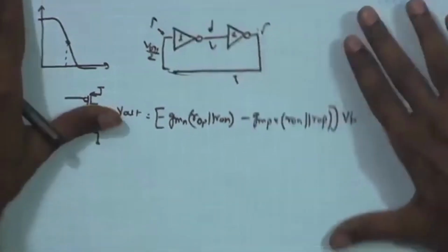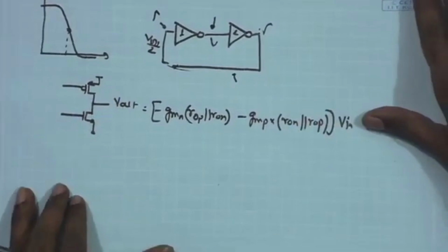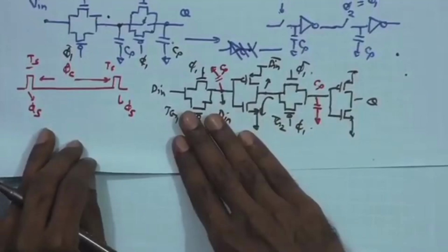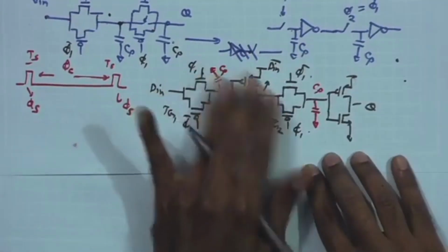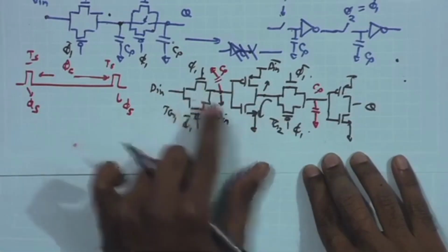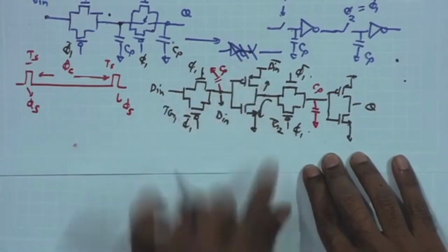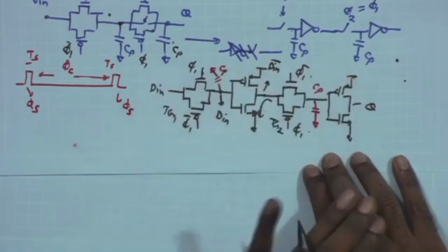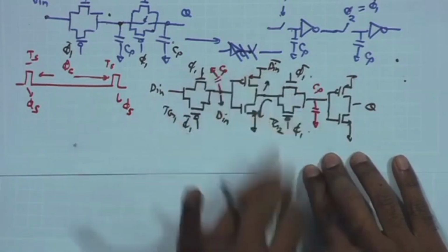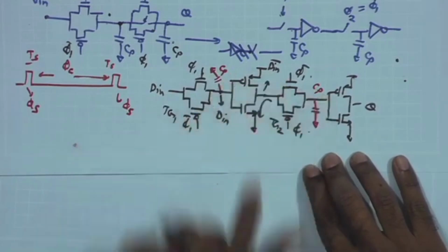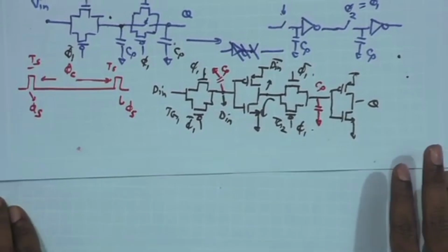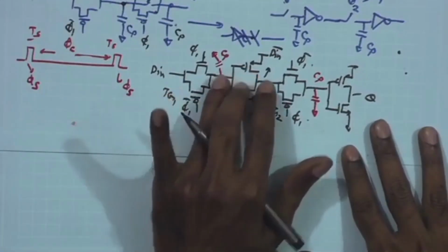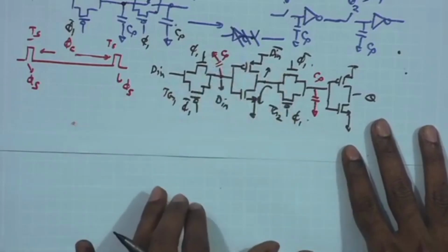For that, I can go back to my latch circuitry that I built, which was not having any feedback, and try to modify it, try to insert a feedback over here. Here we already have a driving mechanism. If I insert a feedback for both these inverters and make sure that they store the data, the data storage is not dependent upon these parasitic capacitances. We can make sure that the overall circuit operation is stable and the values are latched and stored for a sufficiently long time.